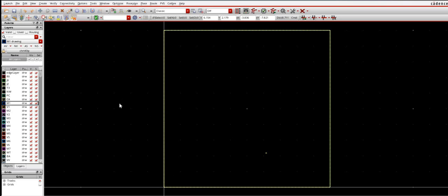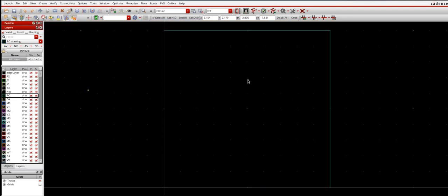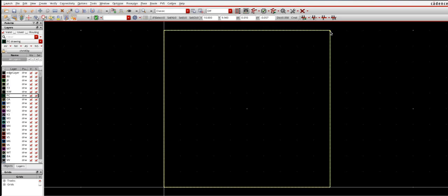Let's take this test case over here in the tool. I'll select poly over here. I'll draw this, my PR boundary, which is 10 cross 10. You can see in the coordinate section, this is 10 cross 10. Just for the sake of explanation, I've created this. So let me select the PC over here, poly, and draw a couple of lines here.